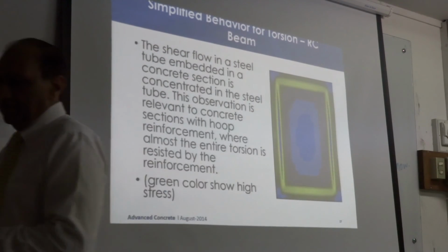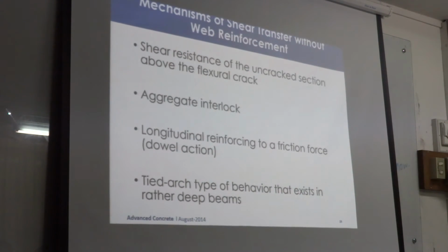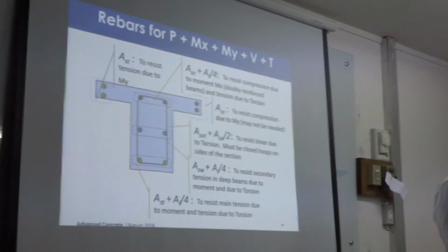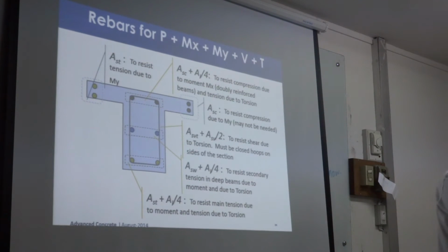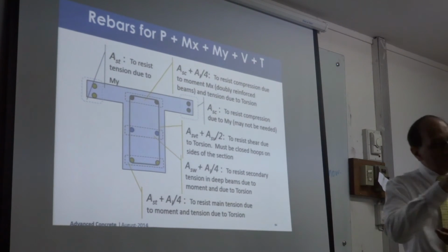So that was the bottom line of this whole concrete cross-section design. Everything else is details. Design the column for every load combination as if it was independent, and take the highest reinforcement at each location for all the combinations and finally come up with a final amount, so that all of the load combinations will be satisfied. Correct? Let's say you have a beam, and one load combination is saying it's a positive moment, and you need tension reinforcement. One load combination is saying it's a negative moment, and you need compression reinforcement. So for compression reinforcement, you calculate compression amount. From tension, you calculate tension amount. Whichever is higher is provided there. So it covers both. Correct? So the same rule goes for every action.